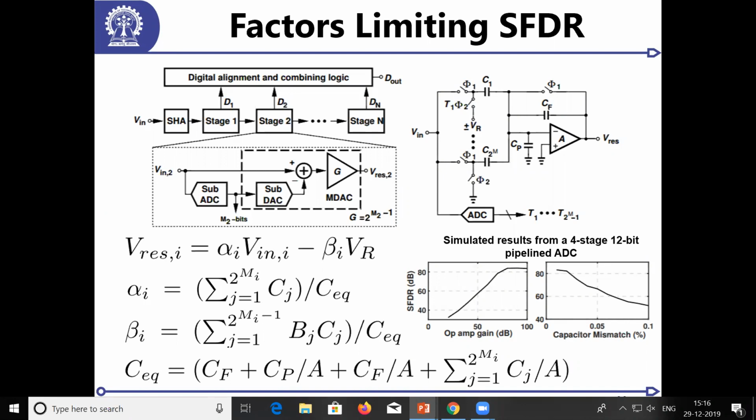If it is not in the same resolution, you will get better accuracy. In the deterministic case, almost you get the same accuracy. Because, okay, I would say yes in the real implementation. Why yes? Because in a deterministic case, you add this dither in differential mode. When you're adding in differential mode, if I want to add minus 0.5, I'll put the capacitor in this manner. If I want to add plus 0.5, I'll put it in this manner.